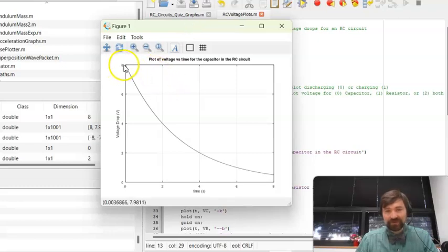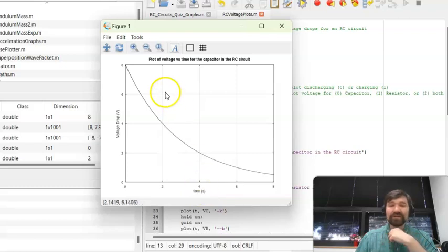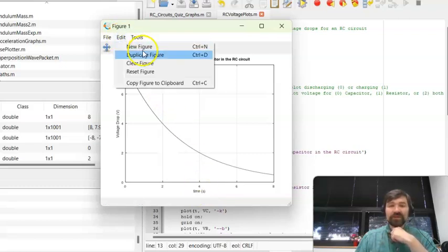So I start from 8 volts. I'm decaying. After one half-life, this is 4 volts, that's half of 8 volts. That occurs in 2 seconds. Okay, a second half-life means 2 half-lives have passed, means we're at a quarter, means I should be at 2 volts, and that's at 4 seconds. So that's the basics of what we have in this code.